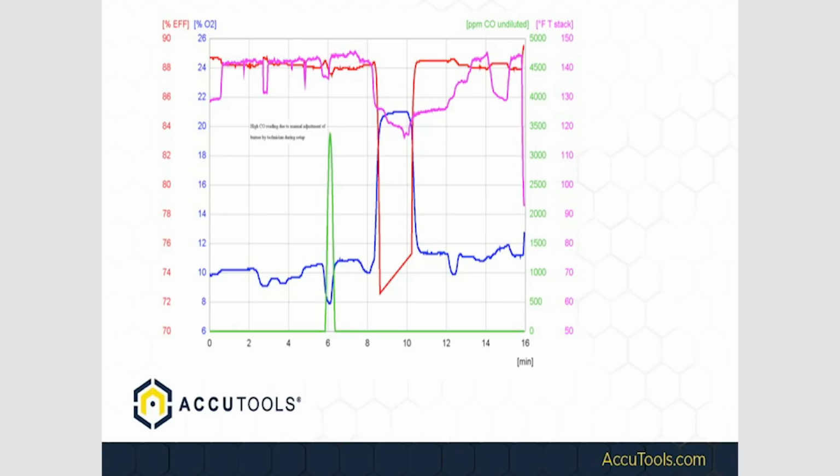And this is where, again, I went out, this is a Lorraine Metropolitan Housing Authority. This is a Viessmann boiler, sealed combustion, bringing in air from outside, probably a million BTU boiler, right? Big boiler. This is a weird case of events out here. What could cause something like that, right? Everybody's out there, there's a pile of pressure switches on the floor, right? Because it's got to be a bad pressure switch, right?